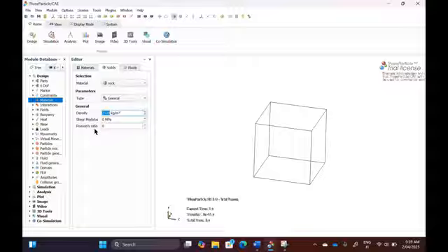Good. Shear modulus. Now again we're back to, you remember last time, we talked about shear moduli, like gigapascal or megapascal, what is it? And we said, setting the shear modulus as low as possible would increase our computational speed. In reality, we have gigapascal. In our system, I would really recommend, and you can also write that down: density you can choose a real one.